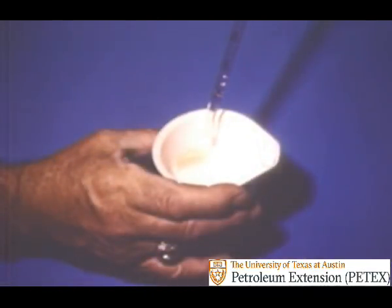For the next test, 1 milliliter of filtrate is added to a casserole and distilled water is mixed in. This is used to determine the hardness or amount of calcium or magnesium in the mud. Calcium-bearing formations are frequently drilled, which causes the amount of calcium to increase and upset mud properties.